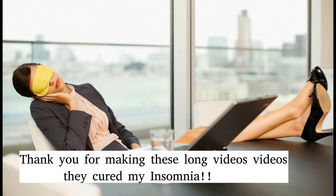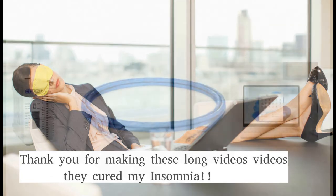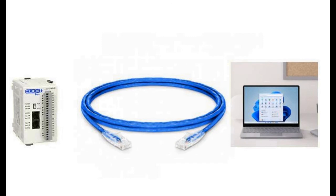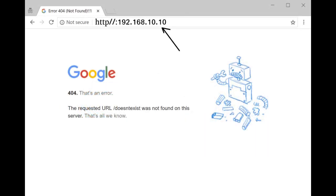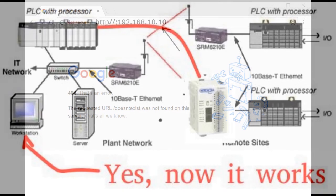Oh gosh, this was a really long video, and if you're still sitting over here watching, I got a few more nuggets for you. First, one time I had to replace a PLC module, and according to the instructions, I was supposed to power the module, hook up a computer to it, and go into my browser and type in an HTTP address so I could access the HTML configuration file within the module. I tried and it did not work. But when we put it into the system, we were able to access it through the computer.